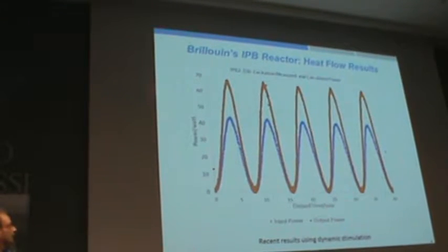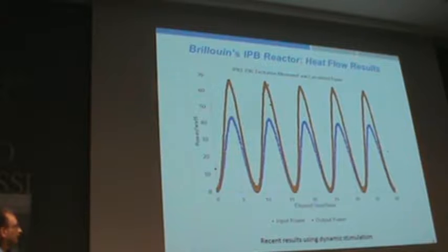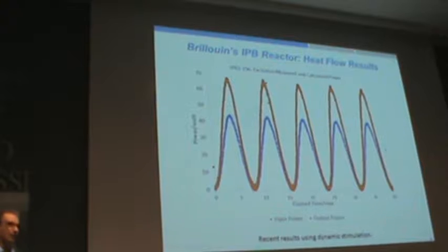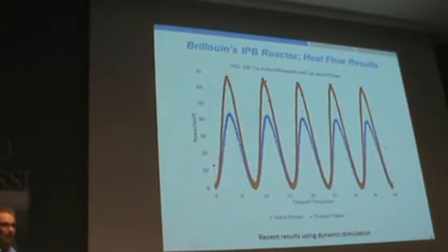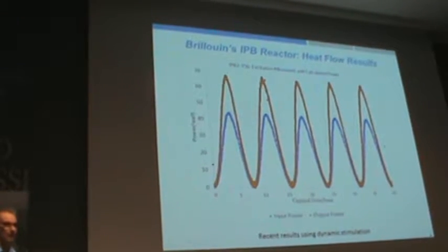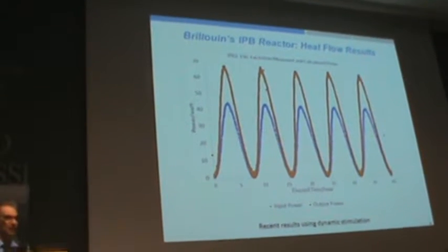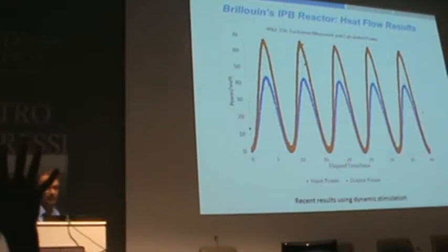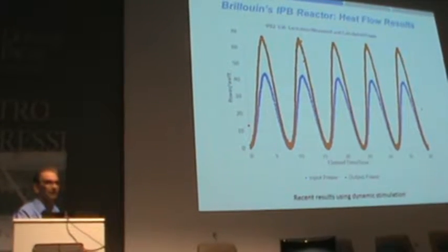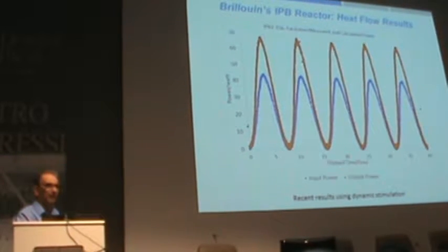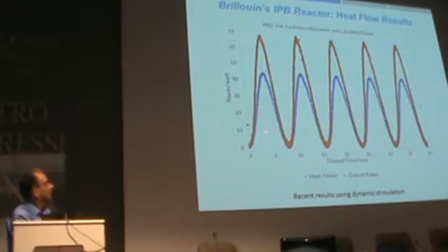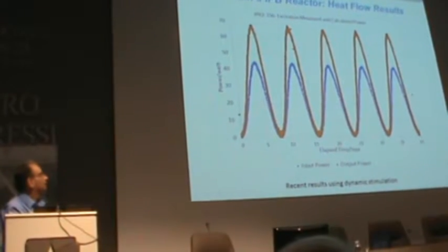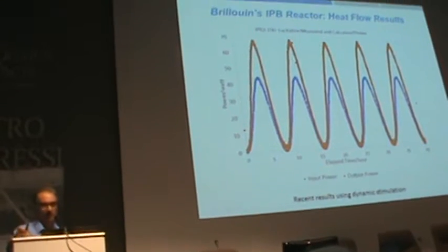You can see a little bit of quantization in the input power and in the output power calculated by taking those 12 constants, putting them into the temperatures that are measured, using that and minimizing, just simply taking those 12 constants, putting them into the equations to give you the power, the calculated power, and that's what we see here in the orange plot, and that's about 1.6 COP.